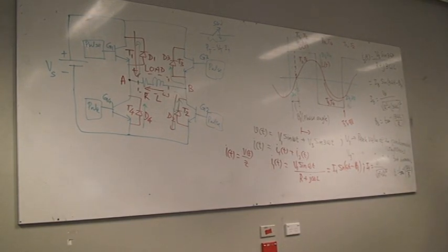So what actually happened, as you go on increasing the order of harmonics, as you can see here, the impedance goes on increasing. So the effect on the current will be much less.